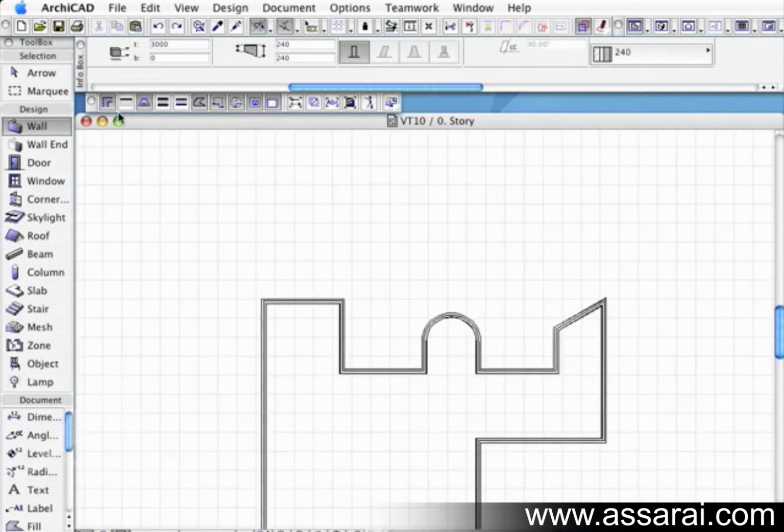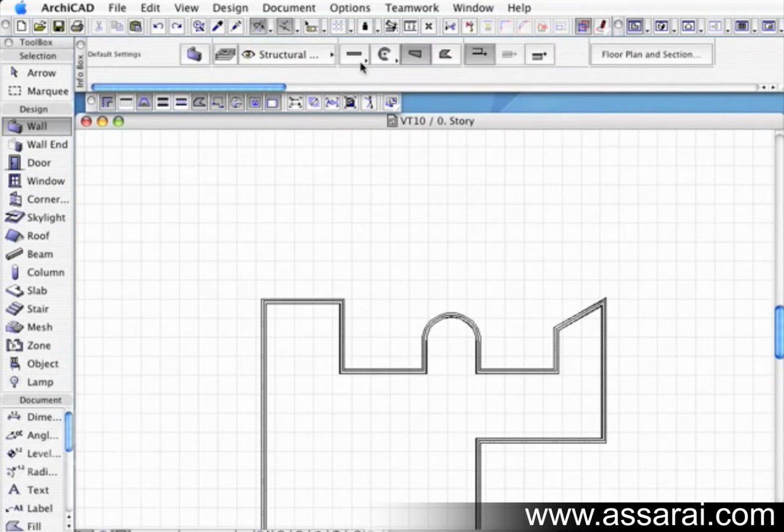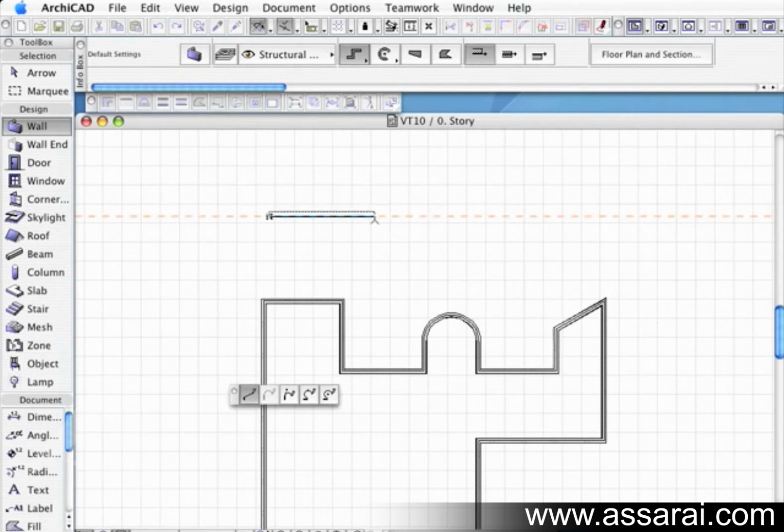Now, when you're placing walls, if you choose the wall tool and choose the method, I might just use a continuous wall method here. We can use exactly the same methodology that we used when we were creating slabs. So I've left mouse click once, I drag out, once again the tracker's not on, so I click the tracker and I type in 6 meters, enter.